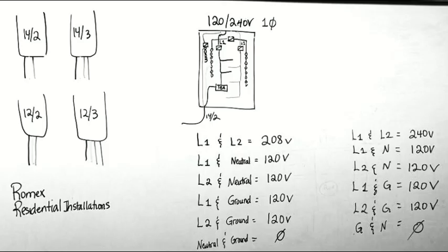That is why all of your receptacles in your home are wired in parallel. So when you take your multimeter and put it in, you should be reading 120 volts on all of them. They all have the same pressure. But they have a limited amount of capacity depending on how many amps I put into the circuit. For example, what is the amperage capacity of a number 14 wire?